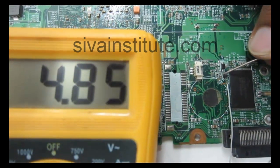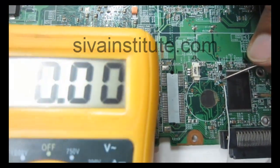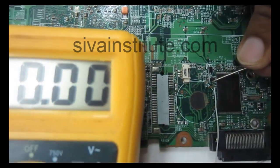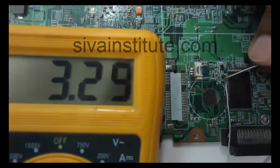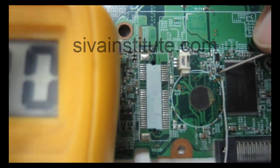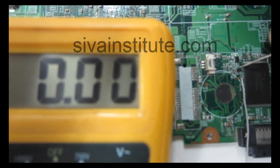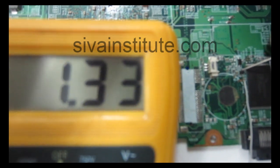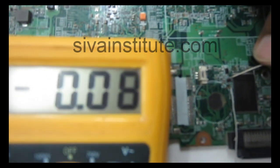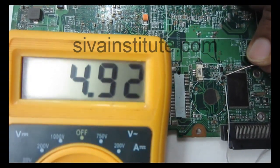Pin number 2: 0 volts. I will give the SPI command: 3.3 volts. Okay, that is at pin number 2. We will see pin number 4. This voltage goes to 0. This voltage goes to 0. With no SPI command, this voltage goes to high.